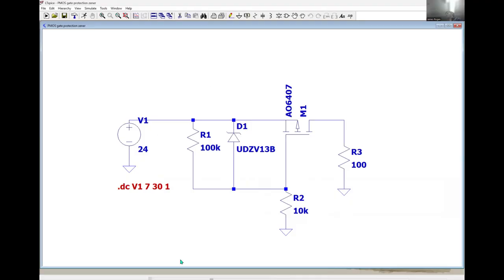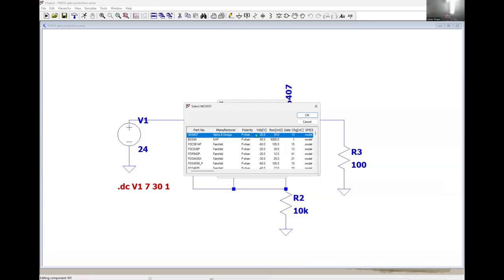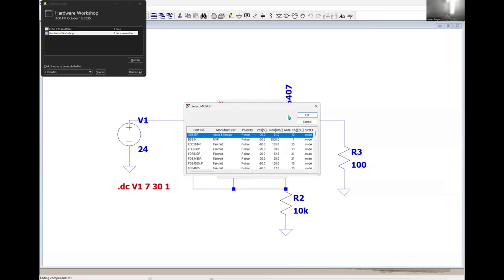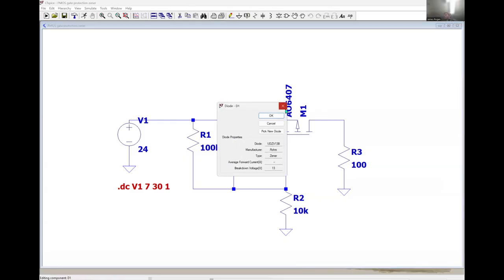So what is LT Spice? LT Spice essentially allows you to draw circuits, connect up components and simulate them using some simulation parameters here. Each one of these components has a model in Spice, and each time it creates an instance of that model, you can assign it different parameters. In this case, I can assign this resistor a resistance value. I can assign this transistor various profiles; I can pick from ones they have available. The same goes for this diode here.